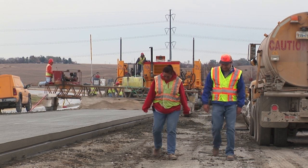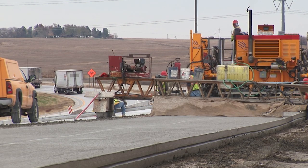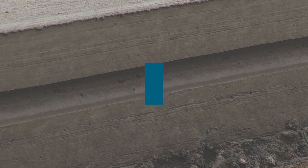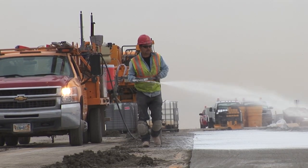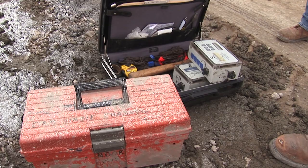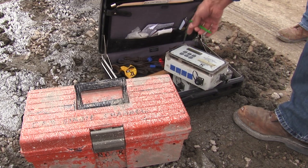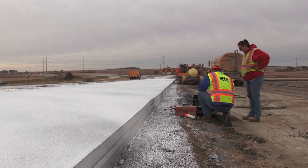Another application where the maturity method is utilized is for mainline slip-form paving operations. Thermocouple wires can be used at any point along the pavement slab. A minimum of 2 wires shall be used in each day's placement. It has been found that concrete does not gain strength at the same rate throughout placement. Therefore, it is recommended installing thermocouple wires at the beginning and at the end of the day's placement, and optionally, installing one in the middle of the day's placement.